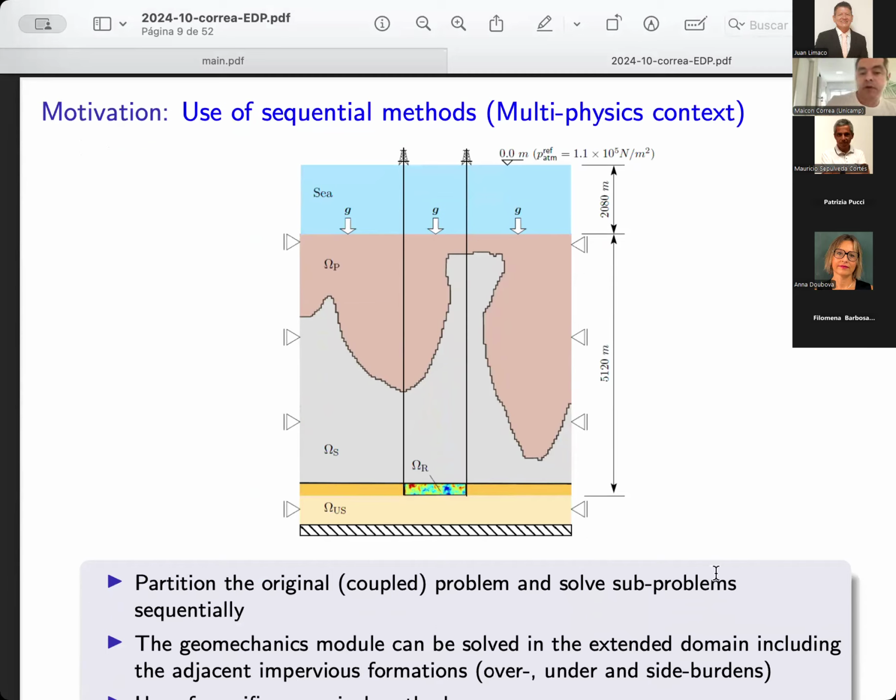And the third one is a little bit different because, as I said, you have gas, and the gas is also inside the oil. So here we introduce another really nonlinear and important function, that's the gas-oil ratio, or the gas solubility, that accounts for the amount of gas that you have trapped in the oil.